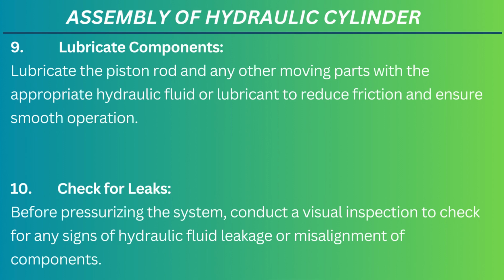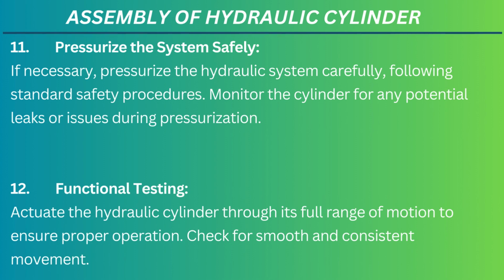10. Check for leaks. Before pressurizing the system, conduct a visual inspection to check for any signs of hydraulic fluid leakage or misalignment of components. 11. Pressurize the system safely. If necessary, pressurize the hydraulic system carefully, following standard safety procedures. Monitor the cylinder for any potential leaks or issues during pressurization.